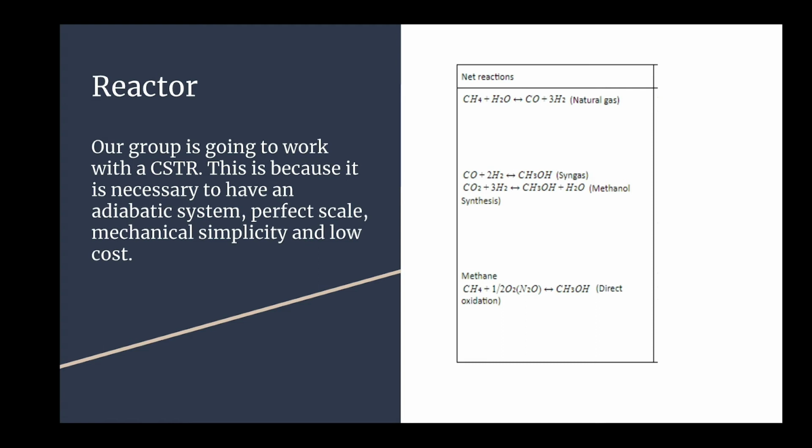Syngas is a general term describing a mixture of hydrogen and carbon monoxide. It can be generated from any hydrocarbon feedstock in different regions. The production of syngas occupies the major investment in the cost of plants. In the direct oxidation stage, the water-methanol mixture is distilled in order to meet the final specifications. It is essential for methanol to be stabilized in order to remove volatile compounds such as carbon dioxide and permit shipment and transport in atmospheric vessels.